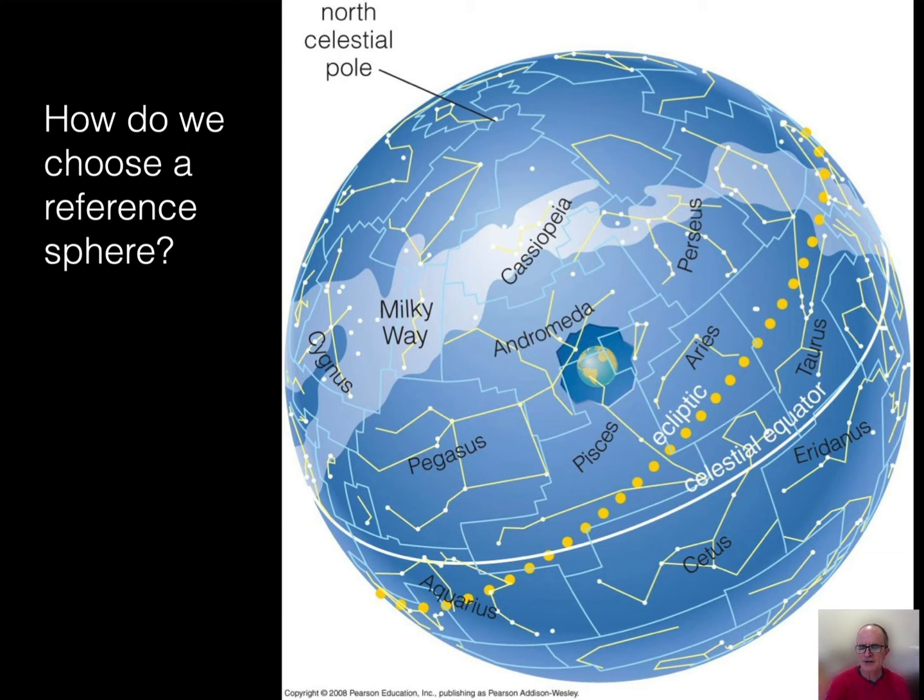So I can make measurements to stars, and if I pay attention to the time at which I'm taking those measurements, I can fix a point on the surface of the Earth. And if I do that from multiple points, I can establish the relative locations of points on the surface of the Earth by measurements to stars. Stars don't move in our lifetime or in the span of civilization. They're in the same location as far as we can see.